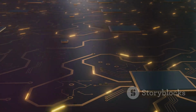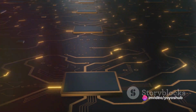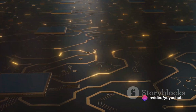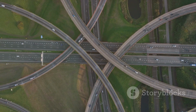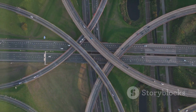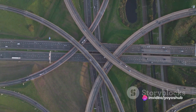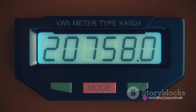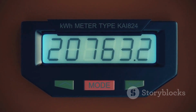The difference in symbols is vital as it tells us about the function of each component. Just like a city map tells us whether a building is a hospital or a school, these symbols tell us whether a component is a resistor, a capacitor, or a transistor. But how do you read a schematic? Well, it's pretty simple. You usually start from the left, which is typically where the power source is located, and follow the lines to the right, which is where the power is consumed. The lines represent wires or connections, and where they intersect, it implies a connection between components.